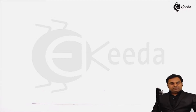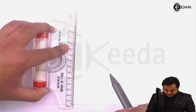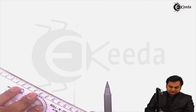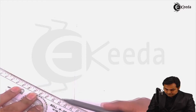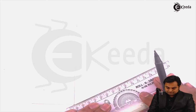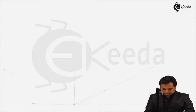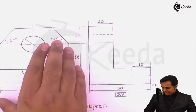So this will be the reference point, and from here I'll measure an angle 30° on both the sides, because in case of isometric drawing, the surface is inclined at 30°, and measuring 90° as well. So drawing a light vertical line. Now, after drawing these lines, that is here the two lines are inclined at 30° and a vertical line. Next,